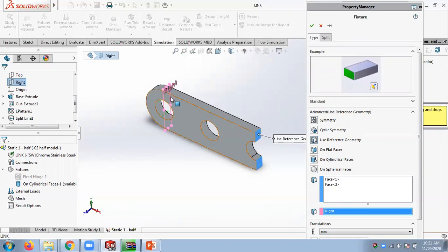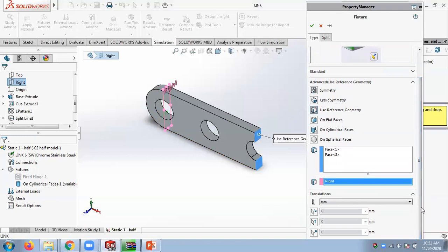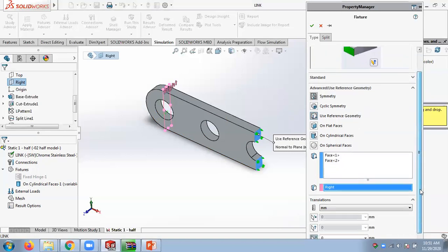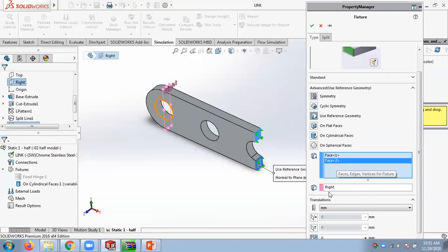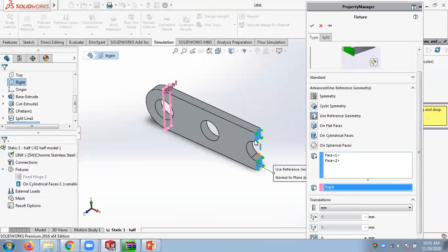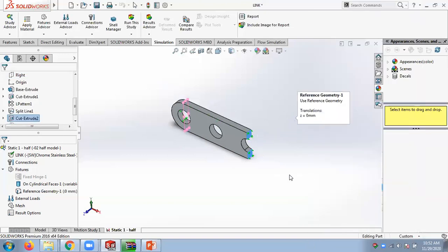so it should be parallel to this right plane. So if I press OK, at least one displacement component. So it should not displace normal to this. So you have to give this one also. So these are the conditions we should give. So we have to select the symmetric plane, symmetric conditions, and select these two faces, and select a plane which is 90 degrees to this symmetric condition. So I'm saying that normal to plane, there is no movement around normal to plane. So when you press OK, it should simulate the other area.